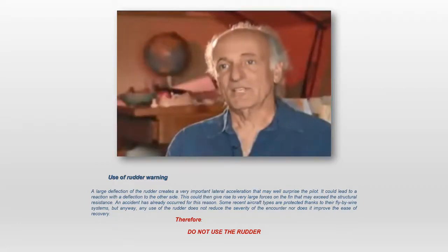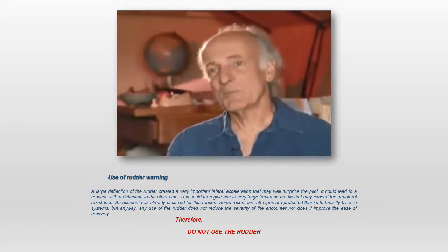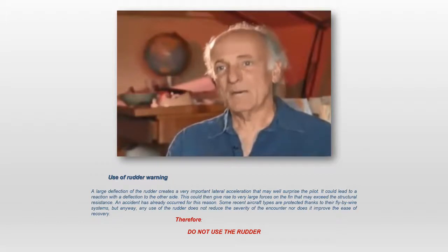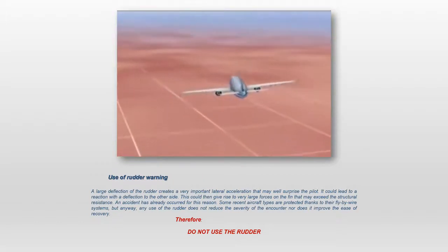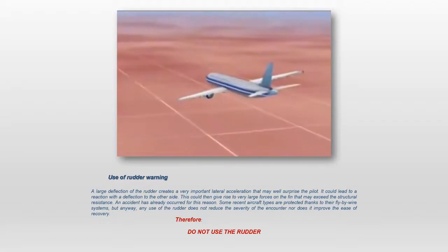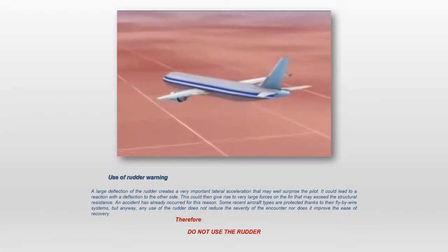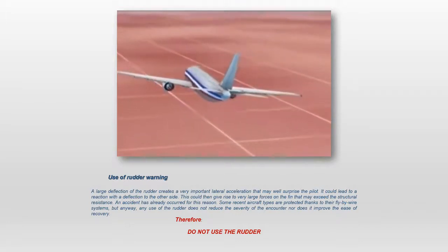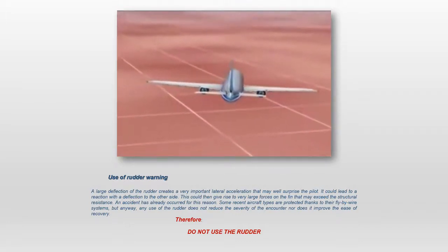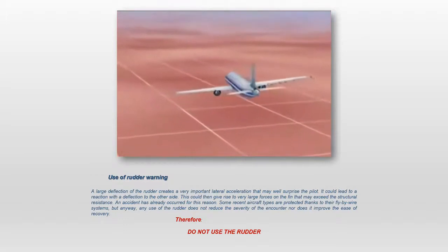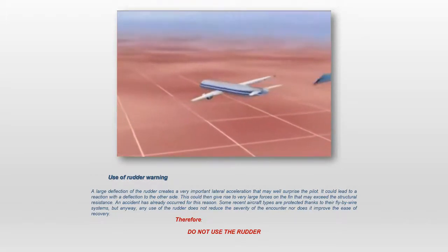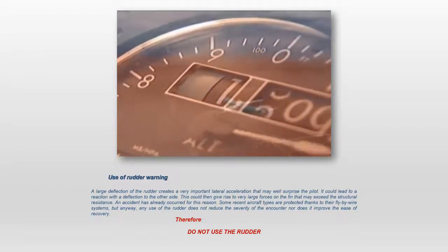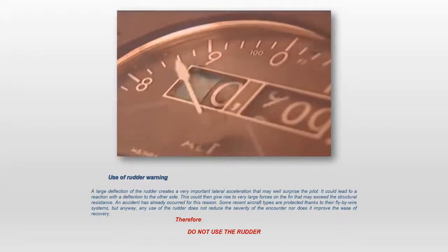He jumped the gun on responding, and as the airplane swung one way, he came in with opposite rudder, and the airplane then swung back and overshot in the other direction because he had put in too much rudder control. And so he then went to the other rudder pedal and tried to correct this. This led to a shocking revelation, dispelling any theory of a terrorist plot, that a pilot could inadvertently cause severe structural damage to an airplane at maneuvering speed.